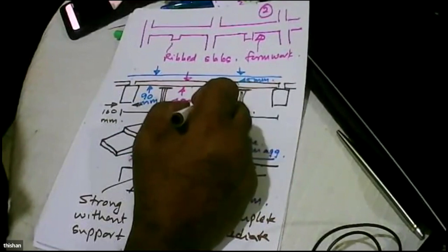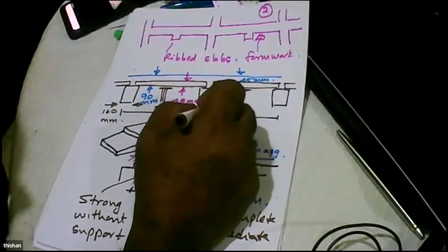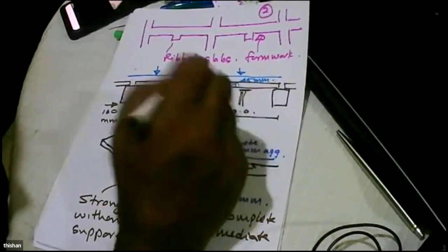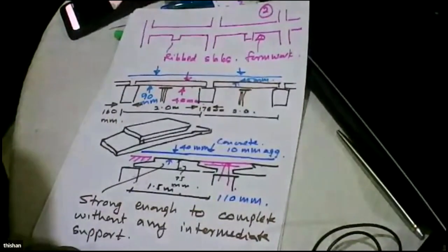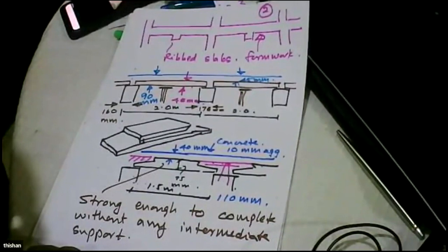okay, now the constructability. Then we thought, if you are going to cast this beam in situ, or we precast it, but we have some lifting equipment like a crane or a tower crane to lift the beam, then the weight of the beam is not a major problem.